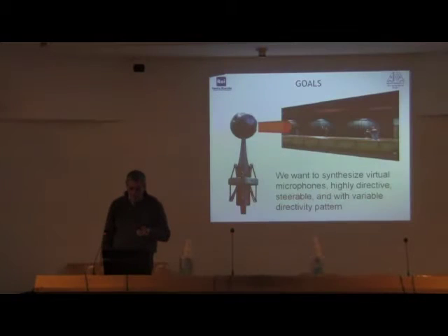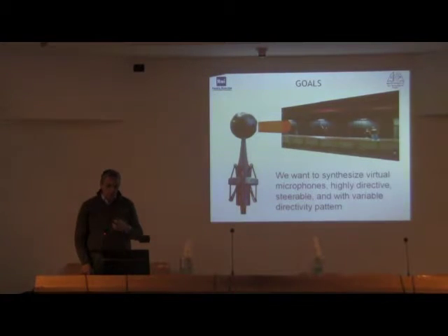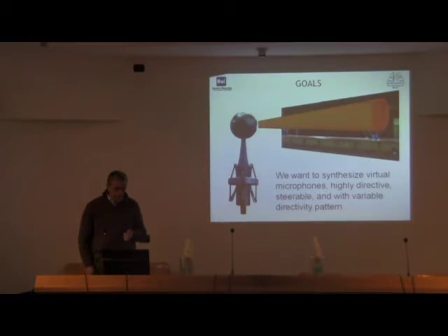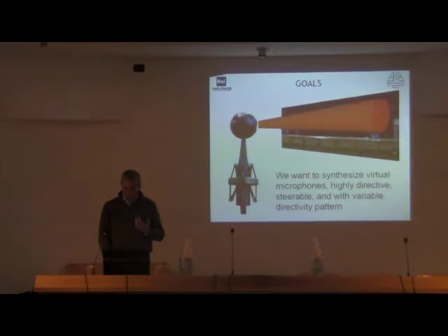And in this case, the goal of the RAI Research Center was to create a microphone system which was capable of creating virtual microphones of variable aiming, so you can steer the microphone by software, and you can also change the directivity pattern of the microphone. And from a single probe, we managed to get currently up to 7 virtual microphones running in real time for broadcasting applications. So that was the goal. As a side effect, we discovered new things.